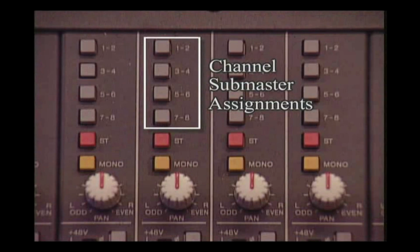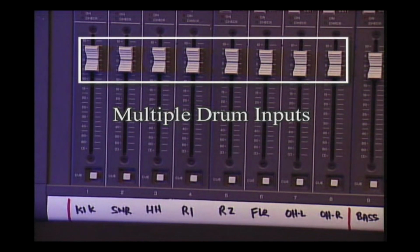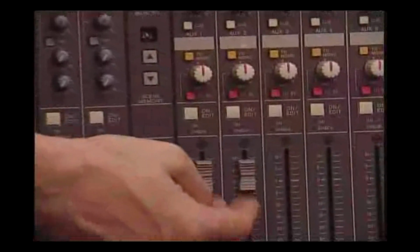These submaster assignment buttons allow the engineer to group or submix any of the 16 channels by assigning them to one of the 8 submaster outputs. For example, many engineers find it much easier to control the overall volume of multiple drum channels using 2 submaster faders. This is done by assigning each channel in the channel's submaster assignment section to a submaster pair, for example, submaster 1 and 2.